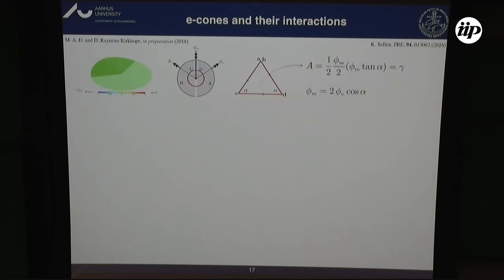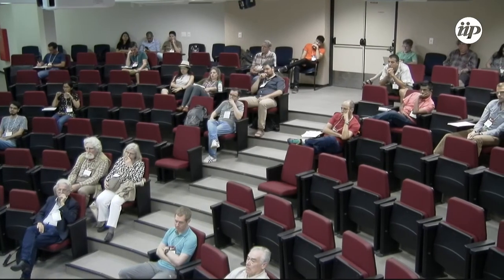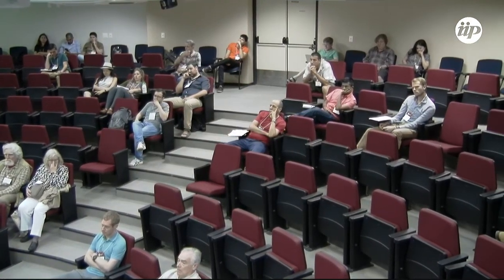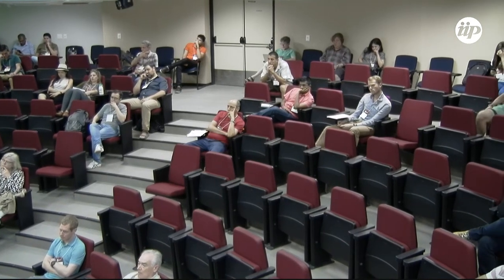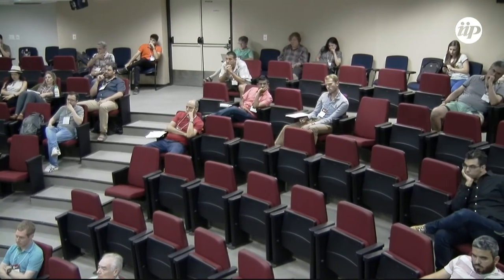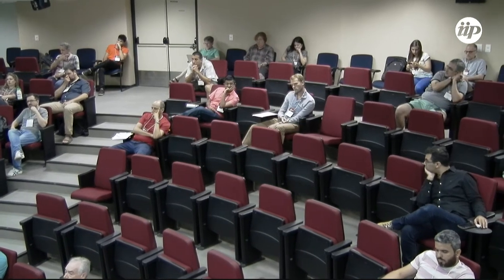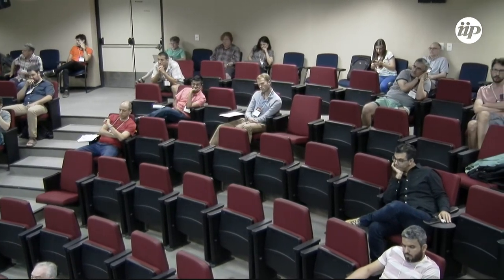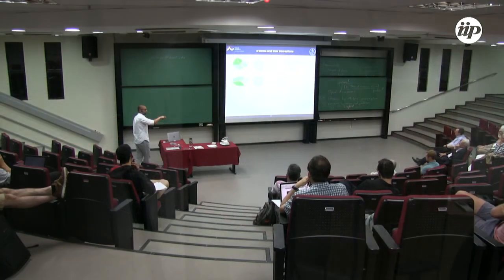On the other hand, in the case of the e-con, you capture an area there, and that area has been shown by Gauss to be proportional to the amount of wedge that you have to impose to deform this structure. But at the same time, you can think of another type of configuration that can hold the same area but has, let's say, less bending energy, because in this discretized case, all the bending energy is concentrated at the folds.